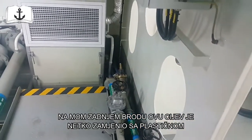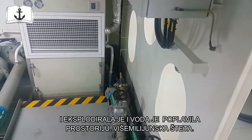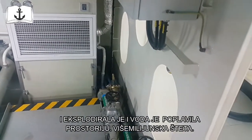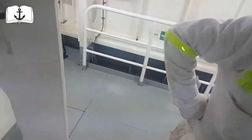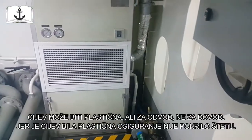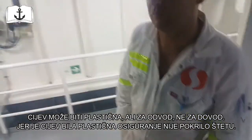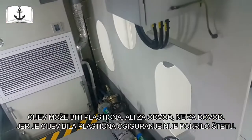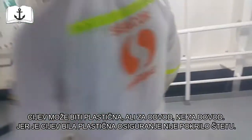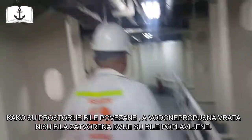burst when we went to shipyard. Someone replaced it with a plastic one. It filled up the thruster room. $20 million of damage. Yeah. Another thing is this unit looks a little bit too small, and plastic pipes are permissible, but it must be... well, no, the insurance did not cover it because it was plastic. If it's a cooling line, I don't think so. Yeah. If it's drained, maybe yes. Yeah. Insurance did not pay for that. So somebody needed to pay this 20 million. Yeah. A lot of money.